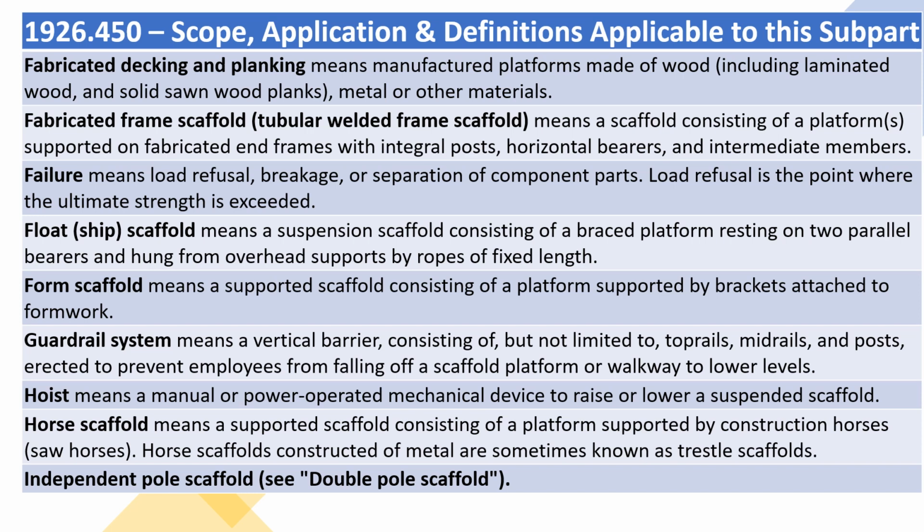Fabricated decking and planking means manufactured platforms made of wood, including laminated wood, and solid sawn wood planks, metal or other materials. Fabricated frame scaffold, tubular welded frame scaffold, means a scaffold consisting of a platform supported on fabricated end frames with integral posts, horizontal bearers, and intermediate members. Failure means load refusal, breakage, or separation of component parts. Load refusal is the point where the ultimate strength is exceeded.